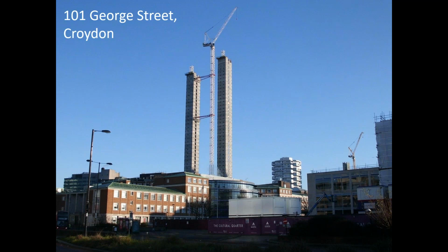In terms of the offset, looking at this photo, a few things to consider. One is the offset of the tower crane mast to the core, which is quite considerable, which could lead to higher reactions at the supports of the ties in the concrete works than would be the case if it was possible to get the mast of the crane a little bit closer to the core.